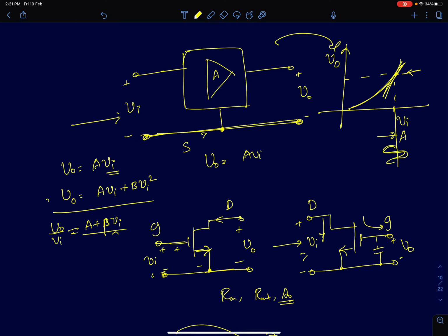So what we are trying to estimate in this lecture is actually the small signal gain of an amplifier. We have already discussed biasing in the previous lecture. After biasing an amplifier, around that bias point or the operating point, we will estimate the small signal gain, the incremental gain of this amplifier. And we are going to assume that to a first order, you can expect that as the gain of your amplifier. Generally it will be lower than that, but you can treat it somehow as the maximum gain this amplifier is going to give us.